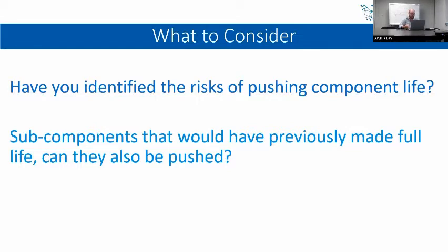So, for instance, a high-pressure fuel pump, if that was to fail in service, there's a good chance that's going to damage the timing gears and potentially destroy the engine. So that would be a component that you would look to do on a midlife strategy to remove it before it can actually fail, because you don't want that to fail in service.